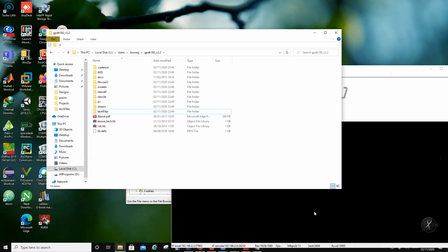So that's there. Now, coming to the questions. Cadence is usually integrated with ADS Momentum. No, it is not. Cadence has a method of moment. Method of moment is a technique. Momentum uses method of moment. So basically, Cadence might use a method of moment technique, but it is not ADS integrated into Cadence. It is a 2.5D or 3D simulator. Method of moment is always a 2D simulation.